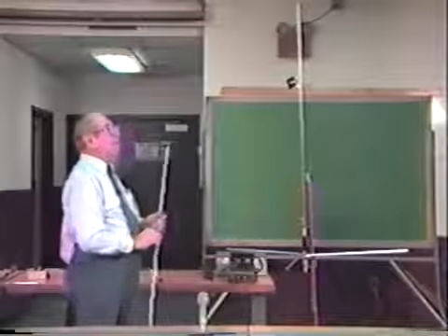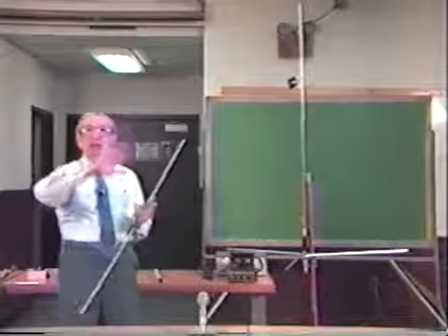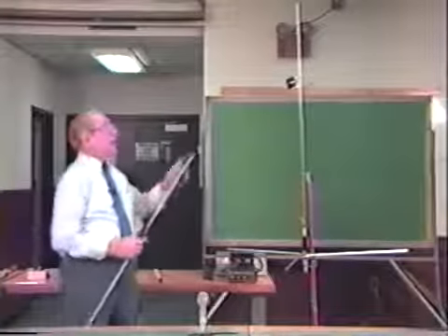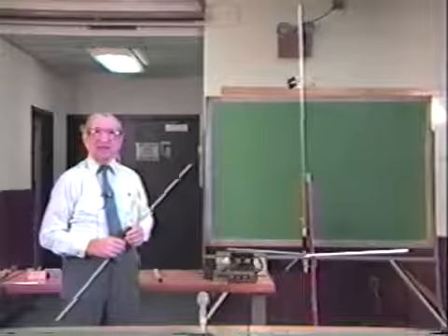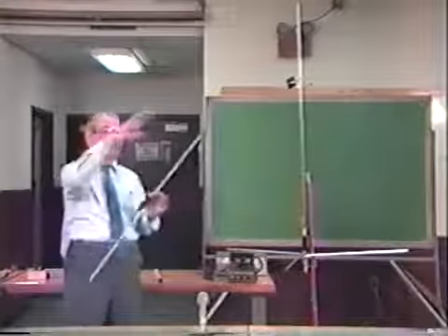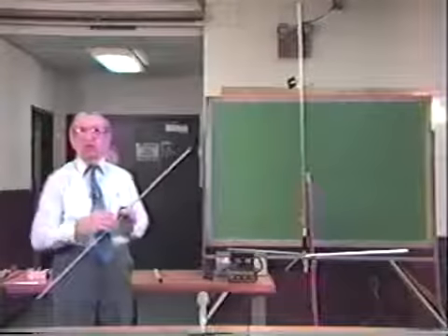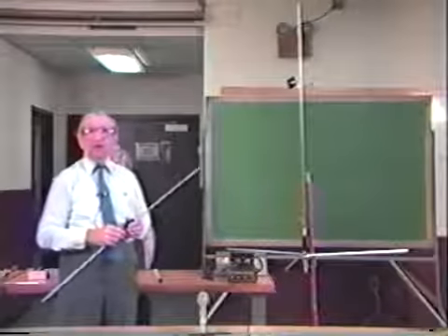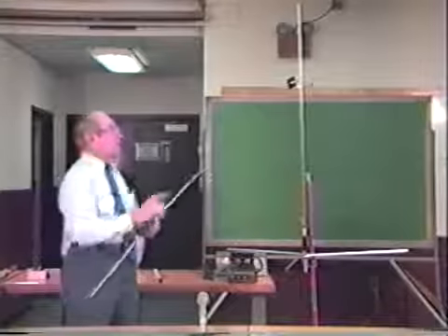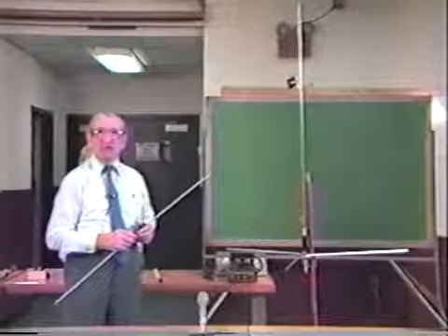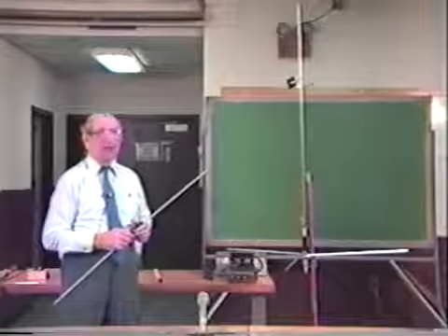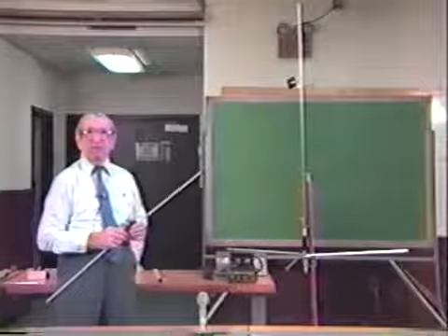And what happens is both radio waves meld together, and you'll find that this type of antenna has a little bit added gain because each one of these radiated electrical fields is reinforcing each other. So the 5/8 wave antenna is a very interesting and very effective vertical antenna for the purpose.